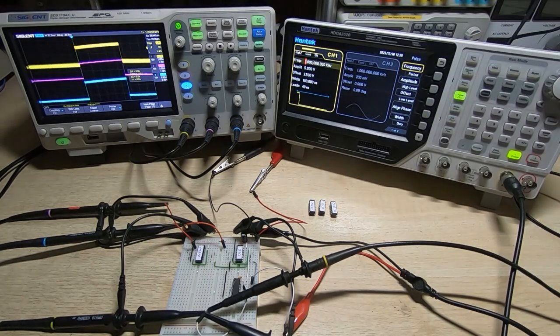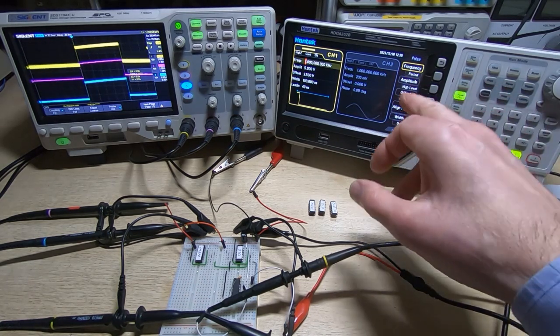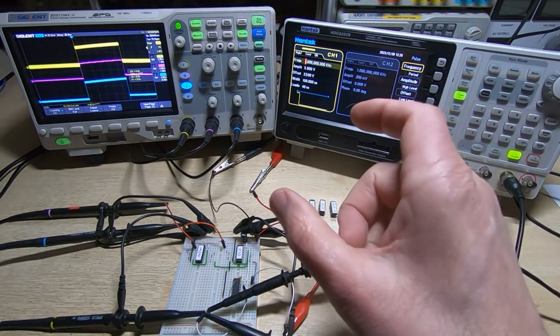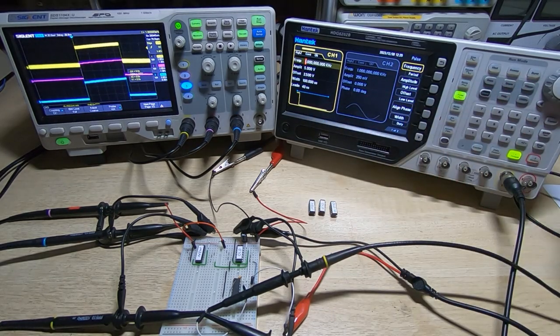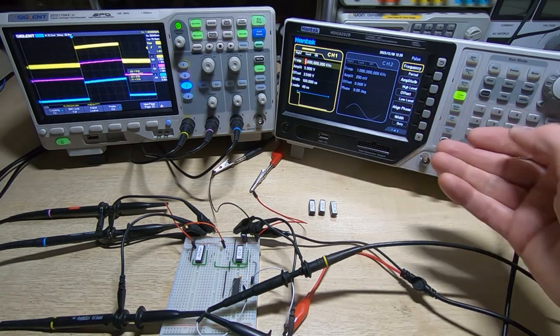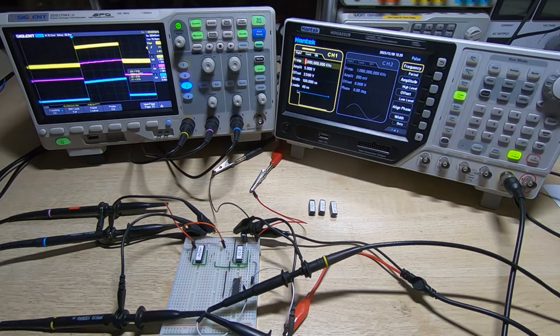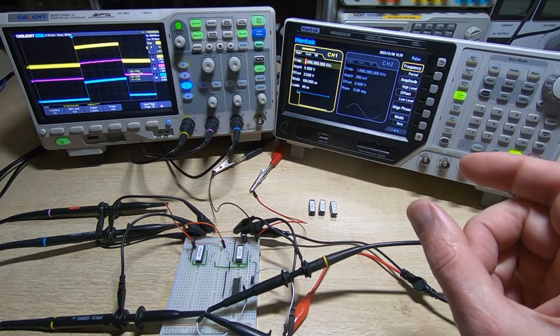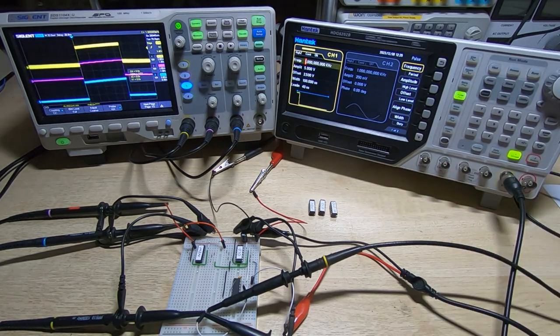So what we'll do is we'll set up the signal generator and the scope in such a way that we are simulating what it is we're looking at. At the moment it's set for 1 MHz with a 100 microsecond pulse width, so it's a pulse we're looking at here. And that's another important point: don't look at it in terms of the cyclic frequency of the signal. What you're interested in here is the pulse length and width that is applied to a certain part of the circuit. But we will assume that we are running at 5 MHz.